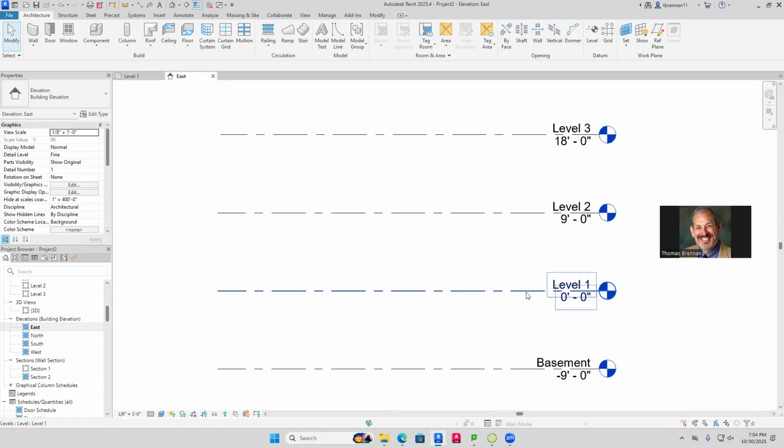So after that, the same is true for level 2. Wherever your foot would be, that actual finish, it's called a finished floor, AFF. Have you ever seen that notation? If you ever see that notation, AFF, it means above finished floor. So that's what that is. And so level 2 is actually right here, and that's the level of the finished floor, and then level 3. So that's what those are.